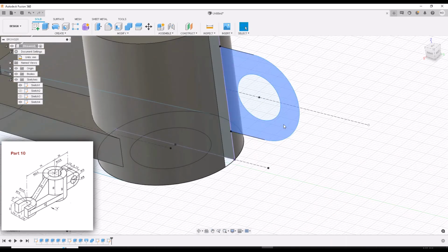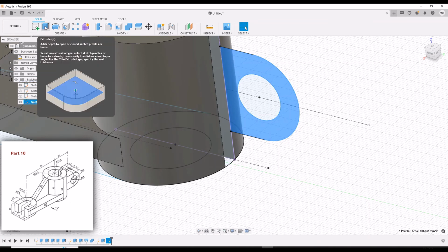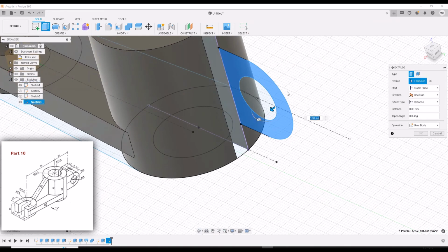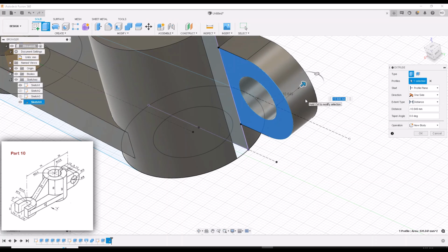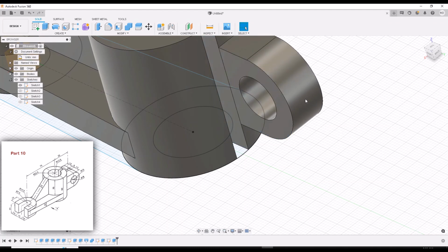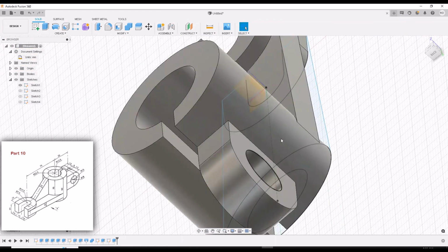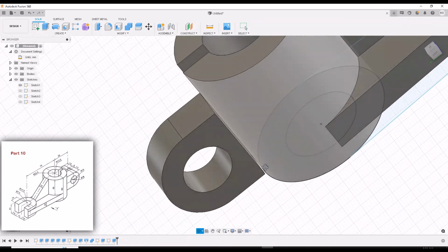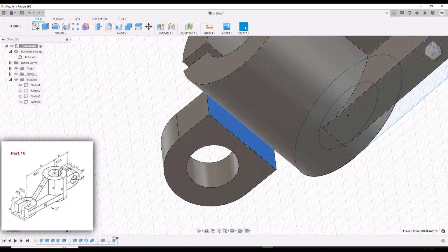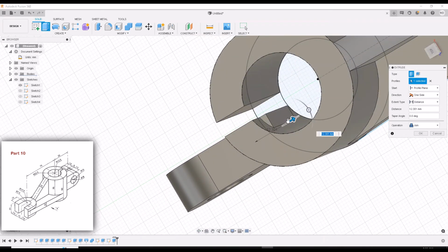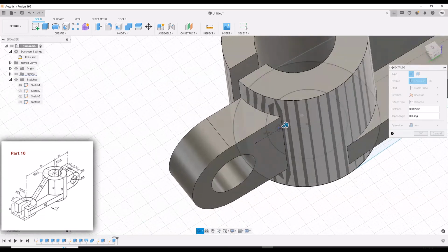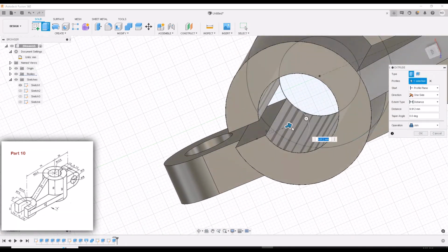Okay. Left click the profile and we want to extrude. Now that extrusion calls for 13 millimeters. So you want to extrude that way, -13. Select enter. Now we want to extrude this part going in to this face. Okay, kind of drag it in. Okay, that's what you want.